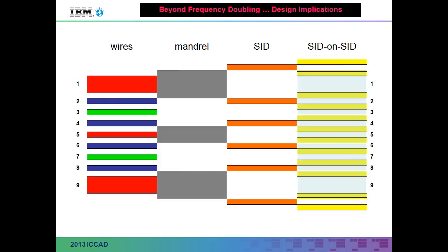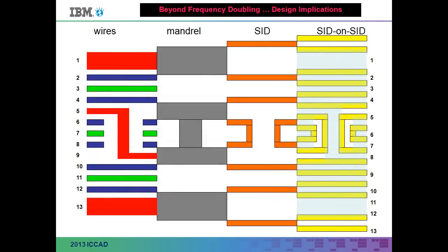So if you want to make anything other than a simple grating, like say you want to make a bidirectional kind of wiring layout, well, first of all, you can only go bidirectional on one of these three colors, and it turns exceedingly complicated, right? If you ever get bored, maybe on the plane trying to fly home, the concept is pretty easy, right? Sidewall and sidewall, you do it twice, you're done. But the design constraints, I think anything other than sort of equal line space grating will just be impossible, right?